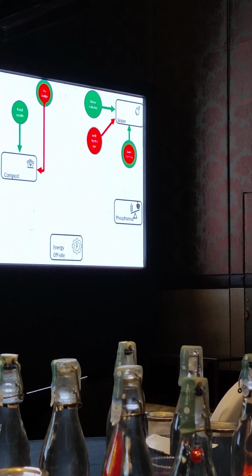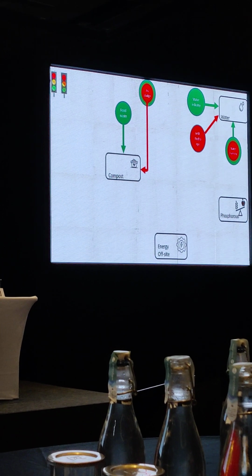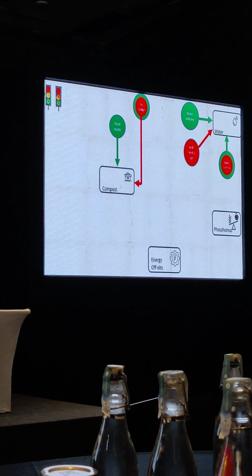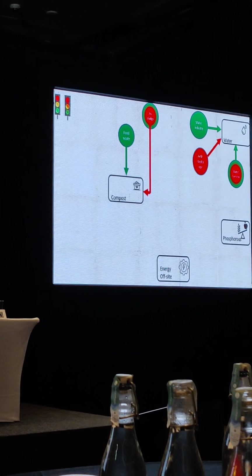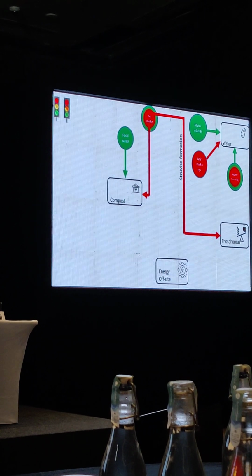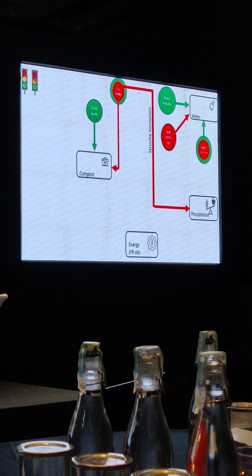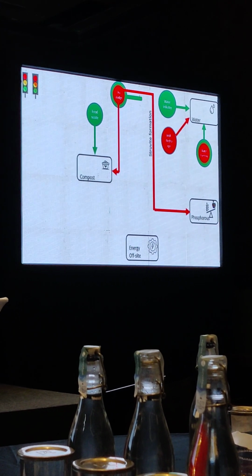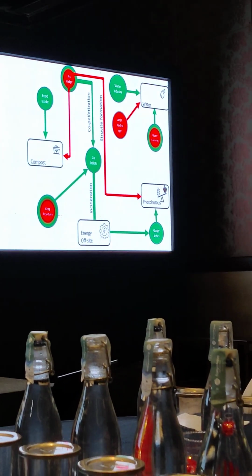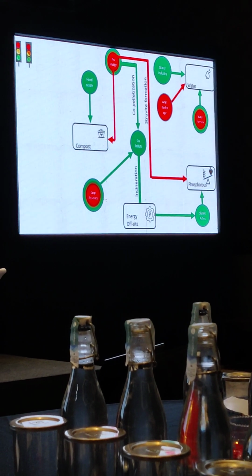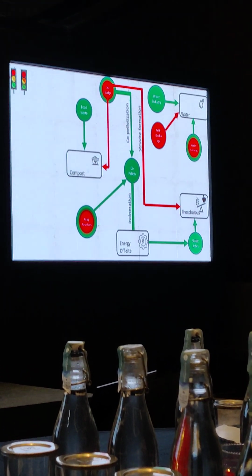If we go for compost production, there are several aspects, and especially toxicity, that say do not use secondary sludge in there. It's full of metals. And this is what they were doing so far. We would do it through food waste. Phosphorus, I have already described. Struvite formation would be discarded for several aspects of the circular potential, and we would instead go through co-pelletization, co-pellets with crop residues that, according to the literature, already provide a sufficient caloric power, and incineration in the energy offsite system.